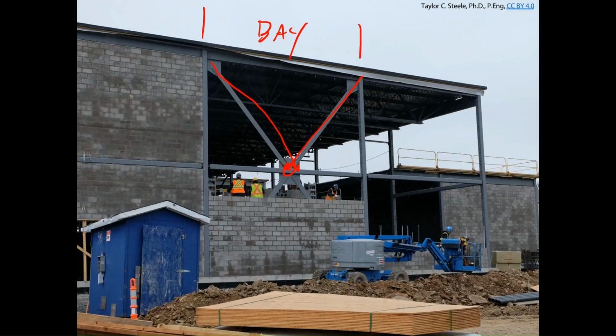And the other thing that's interesting about this bracing, as I alluded to in lab on Monday, is that these kinds of braces are not very good at taking compression forces, right? The resistance to elastic buckling of that flat bar in lab the other day was like 2 kilonewtons. 2 kilonewtons is not a lot of kilonewtons. But in tension, it could carry 675. And so what we're going to see when we're looking at bracing like this is called tension-only bracing. We're going to rely, in this case, only on the tension members to resist the lateral forces coming through our structure, and we'll talk about how to do that.